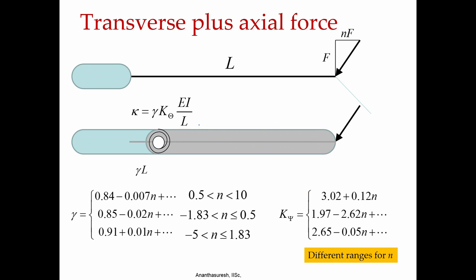Okay. So, what they did was they did very extensive calculation using elliptic integral solutions as well as finite element analysis, where they took a cantilever beam of length L with some Young's modulus, cross section area and so forth, applied the force so that it has transverse component, axial component, both in terms of tensile as well as compressive for the n here, just like what I said. They did that and then they fit circular arcs to the data.